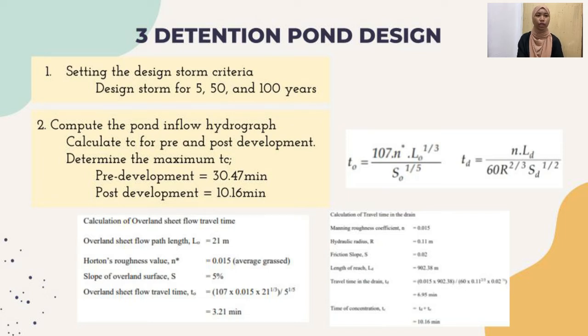Number 2 is compute the pond inflow hydrograph. So we must calculate the time of concentration for pre and post development, and also determine the maximum time of concentration. For this design, we obtained the result of pre-development equal to 30.47 minutes, and post-development equal to 10.16 minutes.